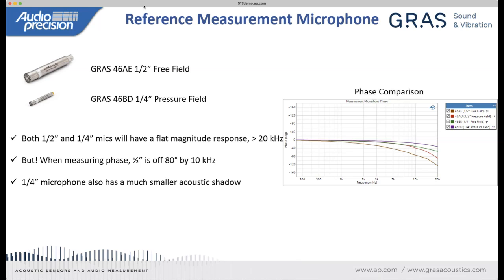What I mean by this is I have a measurement microphone positioned very closely to the microphones under test, and I'm using this measurement microphone as a reference by which I can measure the other microphones. And when I'm doing this technique, there are a few things that come up.